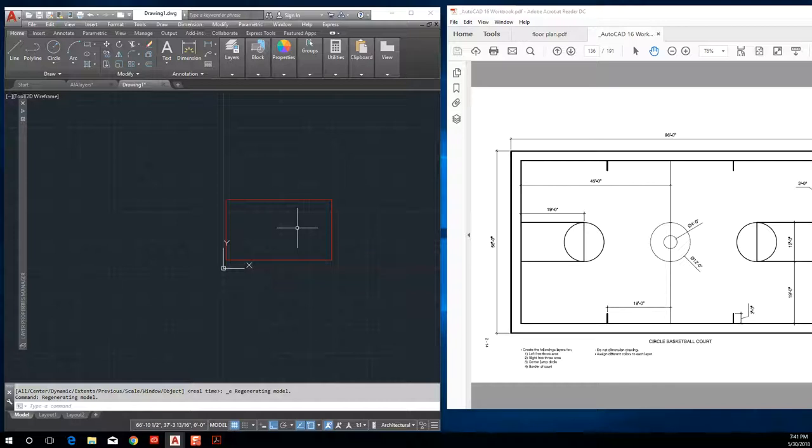Sorry. Nope, you're good. So now the question is, when I drew my line, it was very long, and I had to zoom extents to get it on my screen. But when you were zoomed so far out, it looked tiny and not proportional, right? So you can measure it and make sure it's correct. So I could come in here and type distance, D-I-S-T, enter, and click, and look down here. It is indeed 96 feet, okay?